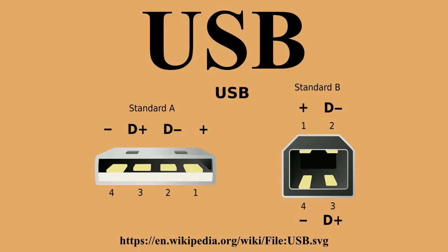High-speed USB 2.0 hubs contain devices called transaction translators that convert between high-speed USB 2.0 buses and full and low-speed buses. When a high-speed USB 2.0 hub is plugged into a high-speed USB host hub, it operates in high-speed mode. The USB hub then uses either one transaction translator per hub to create a full, low-speed bus routed to all full and low-speed devices on the hub, or uses one transaction translator per port to create an isolated full, low-speed bus per port on the hub.